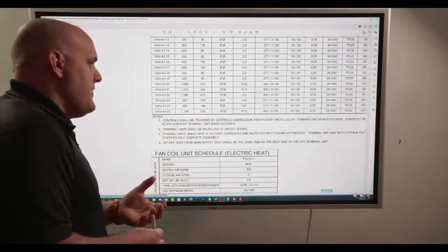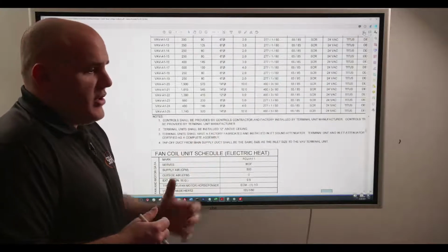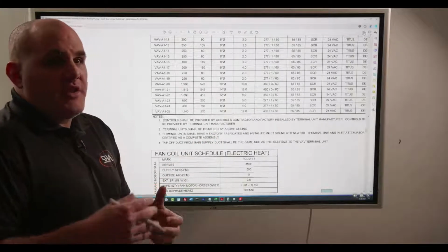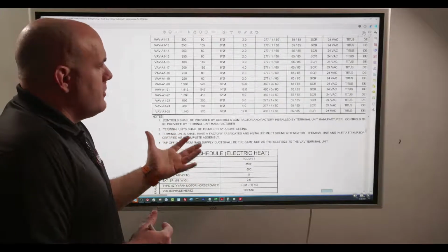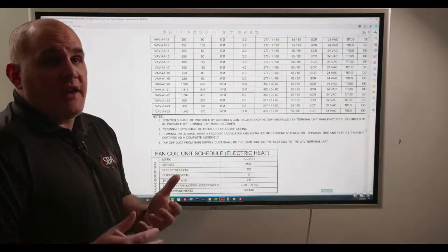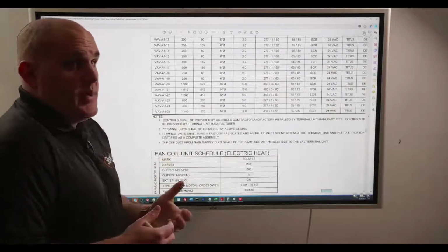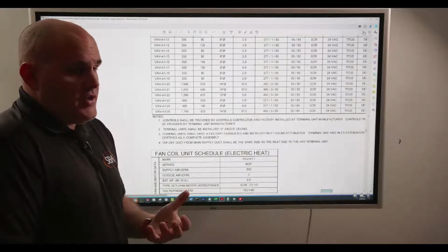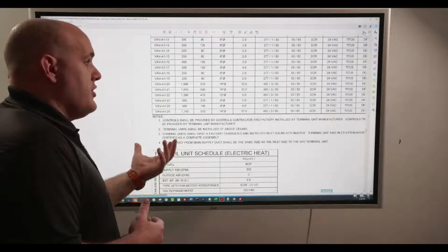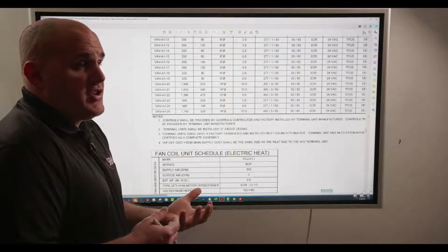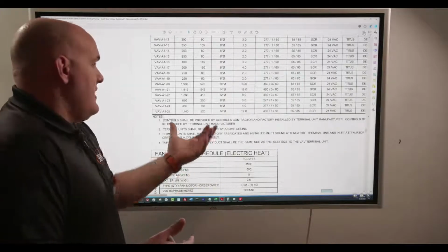The reason why is, if you start at a chiller or an air handler and then work down, you are likely going to either under or oversize your control architecture. Whereas if you start with the terminal units and work up, you're likely to be more accurate on your control architecture. So by knowing how many VAV boxes I have, in this case 25, I can make a controls architecture decision. Depending on what the spec says, I could potentially use an IP-enabled controller in lieu of a supervisory device and significantly reduce cost, right?